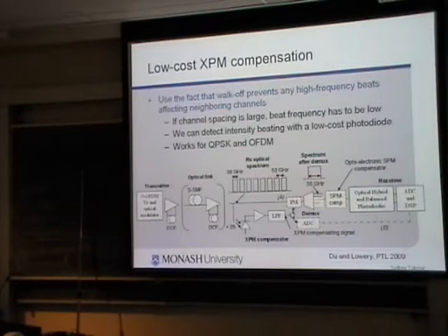So the dispersion, you start off negative, you go up, you go down, you go up, go down, and that sort of thing. So each span has some uncompensated dispersion. That's the dispersion compensation module. And that's typically used in many communication systems, long haul ones. People spend a lot of time trying to optimize that sort of pattern.